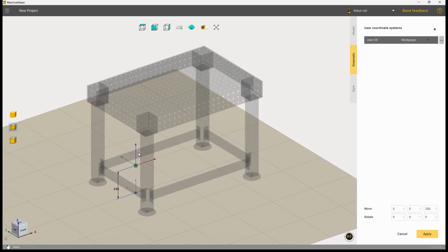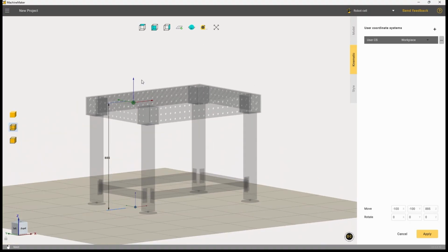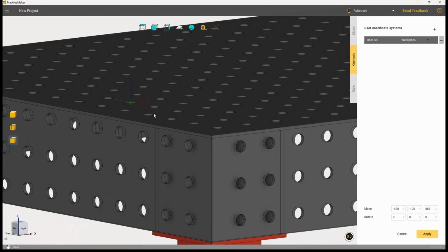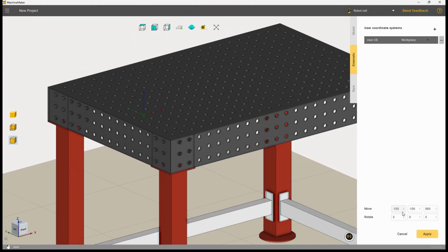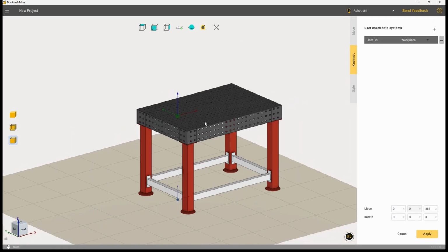Define the robot's mounting point. Snapping is available and you can switch views as needed. Remove any XY offsets and name this new coordinate system to keep things organized. Mark it as a mounting point for another mechanism, not a workpiece location.